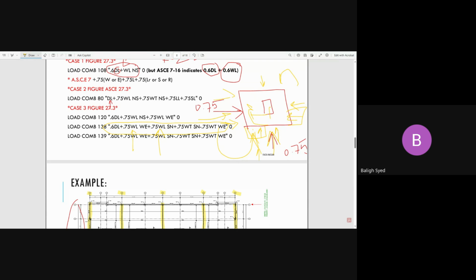Does it make sense what I'm saying? You are taking the worst possible load effect on your structural system. You are combining the wind loading from two directions, and then you are also taking the worst effect of the wind torque from those two load combinations. See here: wind west to east, wind torque west to east, wind load from south to north, wind torque from south to north.